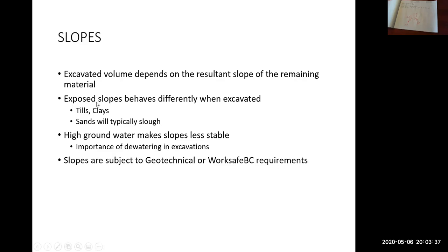So exposed slopes behave differently when excavated. An exposed slope of tills or clays will typically stay like that. So maybe it's a one-to-one slope of till or clay, it'll stay like that basically forever.